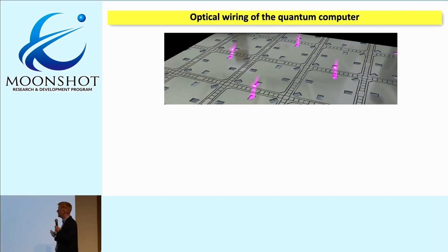And one of the great things that we have out there is the possibility to make use of technologies that are being developed for other fields. And one is these integrated waveguides. And the concept diagram, this is a picture from Lincoln Labs, who were the first people to do these sort of experiments, is that underneath the electrode layer, which is forming the electrical fields for the trap, is some sort of photonics layer which is wiring up the light. And then light should diffract out of that plane when it's needed to hit the ions.